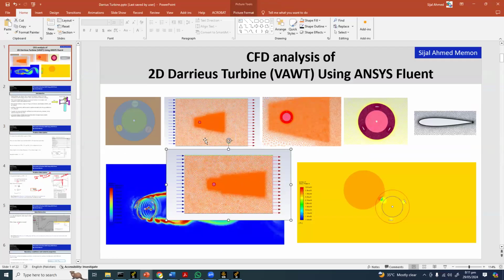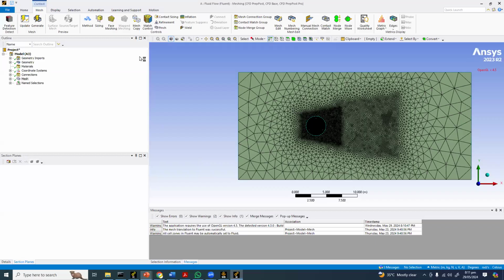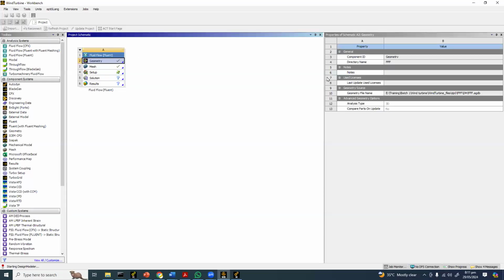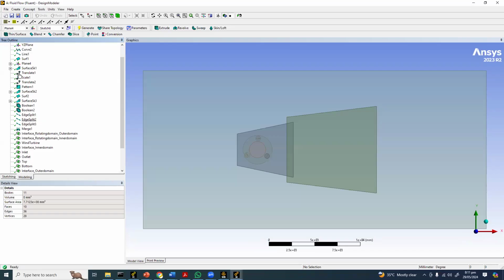See that right now in our current case, our mesh density is high in this region, but in this mesh it is almost up to the outlet. Okay, you can extend the region, no problem. I can go back to my geometry software and extend the region anytime. Making two regions will be beneficial because now we can adjust the two element sizes over there. So for that to change, we just need to go to plane number 4, I think.